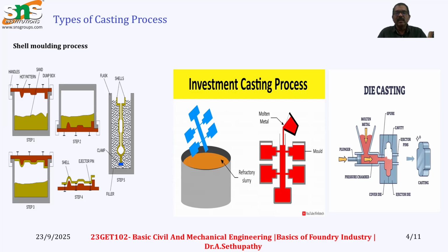Then die casting uses low temperature metals like aluminum and lead, which have small melting points. Two types of dies are used in die casting: one is stationary and the other is movable. The stationary die is fixed in the machine and the movable die is fixed in the ram. They are closed together and have a cavity for the needed size and shape. After the molten metal is injected into the cavity, we wait a fraction of a second for cooling.